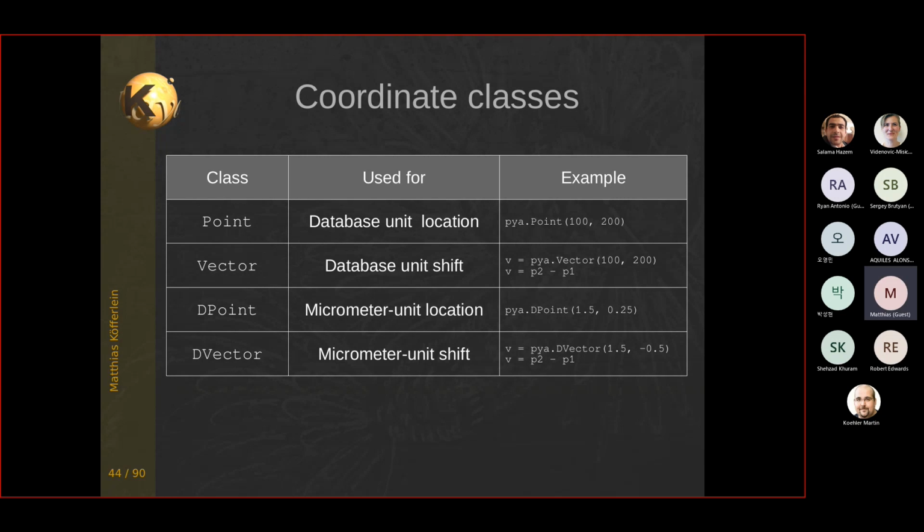I have a question. How do we manage the floating point error stuff? Like we give the example of 0.1 plus 0.2 is not 0.3. Okay, you mean the rounding effects and so on. KLayout internally always applies some fuzziness. So, for example, if you ask whether 2 points are identical, and you have 2 floating points, we define an interval. You don't necessarily have to care about this. KLayout does it for you, but it uses an interval which is, I think, millionths of a micrometer. So it will always apply 1e minus 6 as a fuzziness internally.